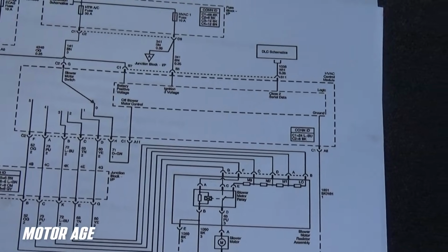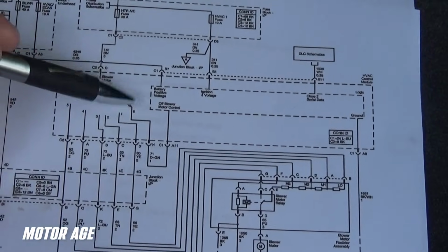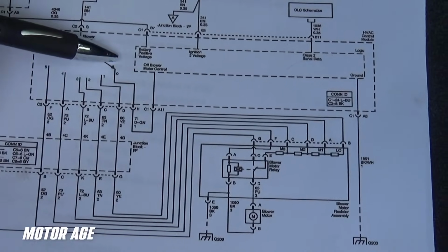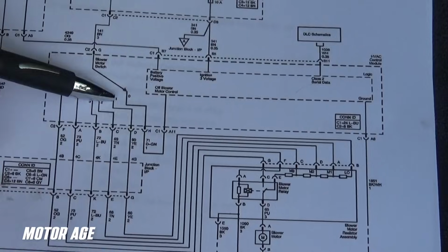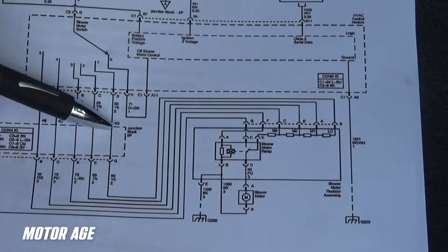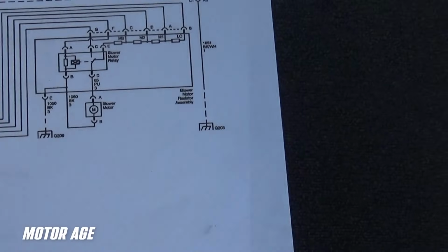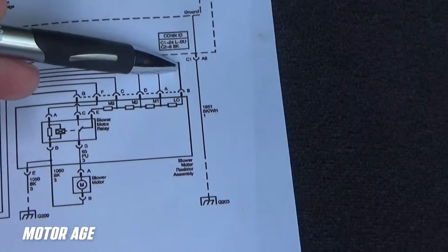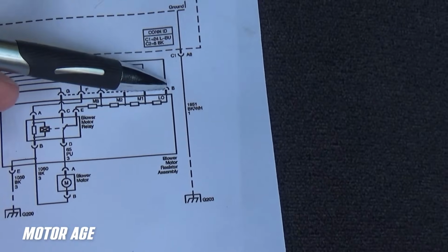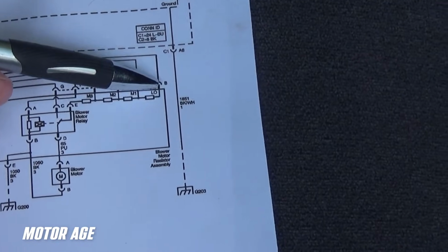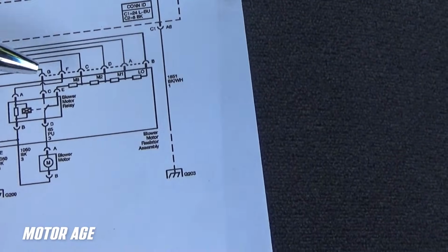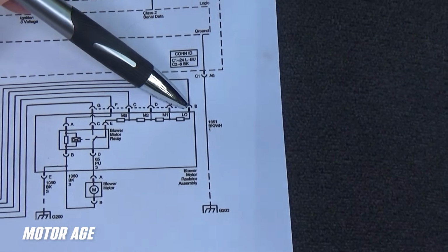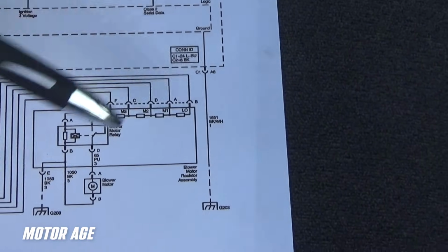Here's our blower circuit as we described earlier on the computer. And we're going to be over here in position number 1. Position number 1 is going to allow voltage to travel through the yellow wire over to our resistor. Now, when I turn it on in this position, the blower does not work. We have to first determine, do we have voltage there? What are some of the questions we can answer? Is the blower functional? Of course it is.